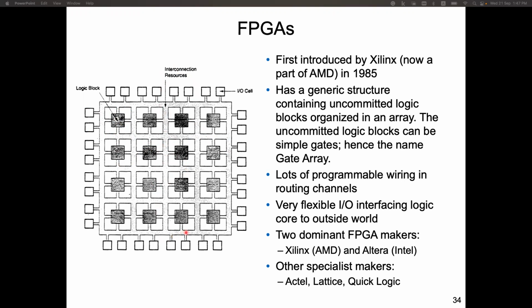It also provides lots of I/O cells. And these I/O cells can be very flexible. Say there are different logic level standards. Say for TTL, the supply for high is 3.3 volt. Or CMOS can be different. So there are different definitions of low and high voltage levels. And for FPGA in general, these I/Os can be programmed, can be configured by the users for different standards.